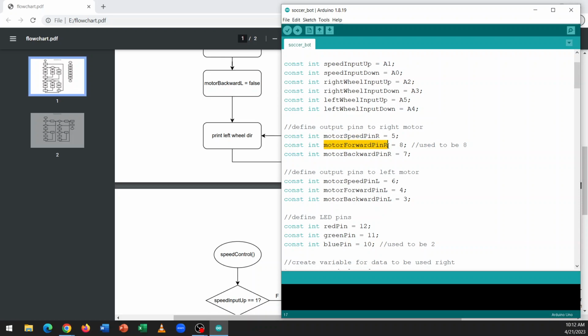And these are the direction pins. Direction pins only go in pairs, and they will both be sent to your driver also. You have a forward pin and a backward pin, and these two pins control the set of motors on your right side. The values for these pins will always be high or low, and will always be opposite if you want the driver to drive the motors.